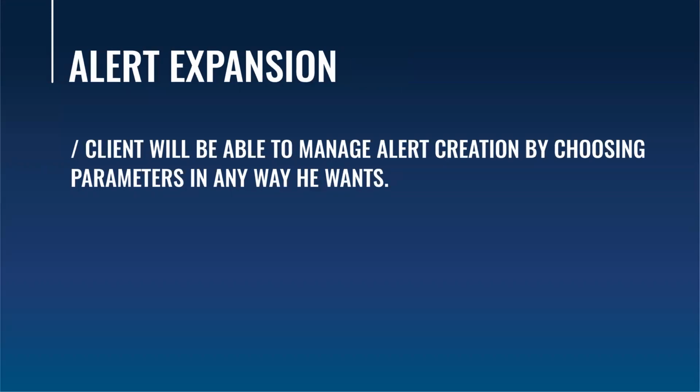So for example, let's say you have a sensor that measures temperature in a room. You connect that sensor with a Teltonika router that has Bluetooth, and you send the sensor data to RMS. You can configure an alert that if the room temperature coming in from this router, from this specific sensor, reaches a certain point, then activate another router's, let's say, digital output or digital input, and turn on some kind of, I don't know, air conditioner. The possibilities with this kind of interconnectivity and functionality are really just limited by imagination.